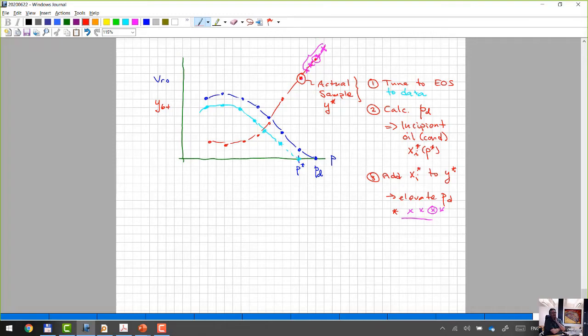Okay. All right. Thanks. But if you're doing compositional simulation, you could just put those compositions in the model as sensitivities, or create black oil tables. I mean, it would just be one black oil table extension. You'd have a single black oil table. The key is that you want to create extrapolations that when you deplete it back down to P star, you get the same composition, okay? And you get the same depletion performance below that.